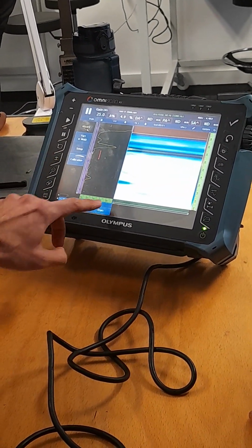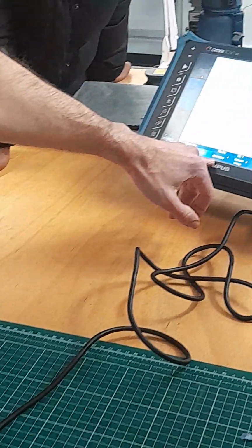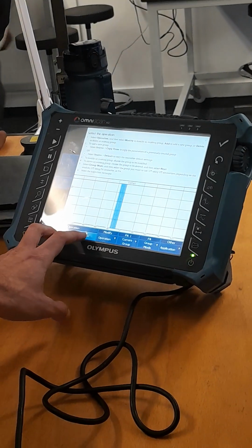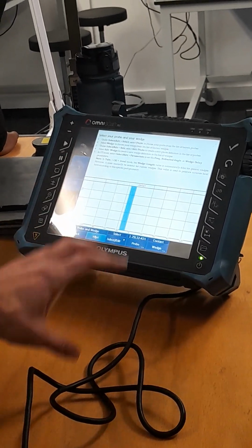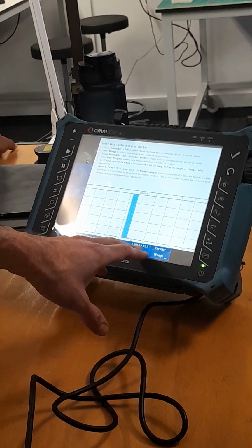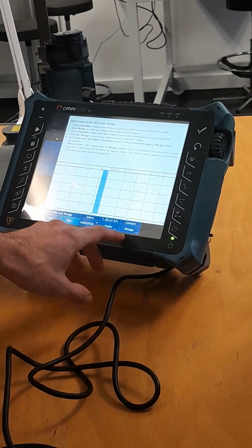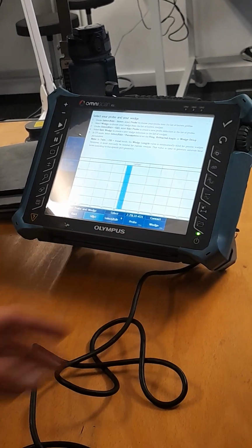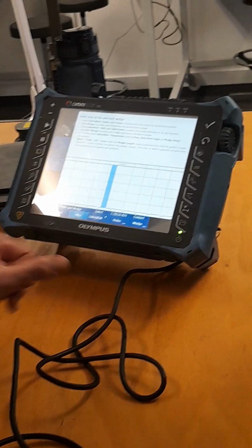If we go to the setup, we will set up what the probe is. Okay, modify phase array group 1. This is to give names to your groups. Select a probe. It has got it in the library. So this is a 2.25 L32 probe, and it's a good thing that we started again because it says wedge contact. So it doesn't know at the moment that it's got this. It thinks it doesn't have it, and it's in contact mode.